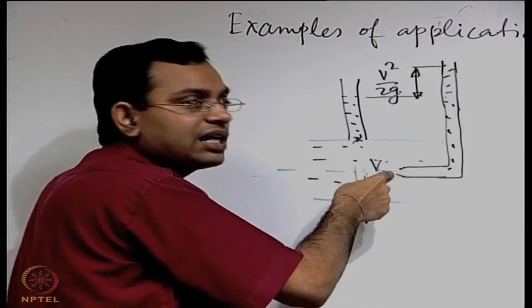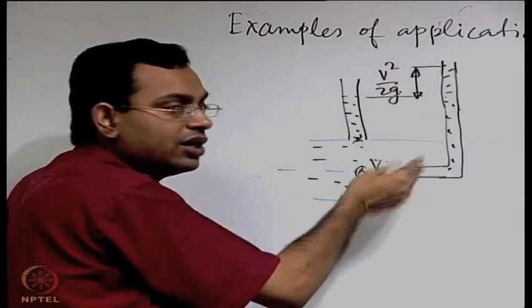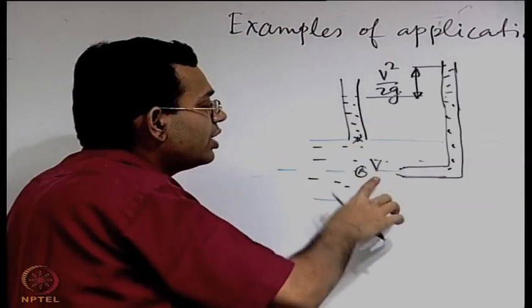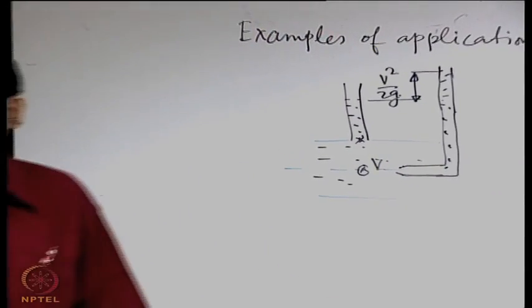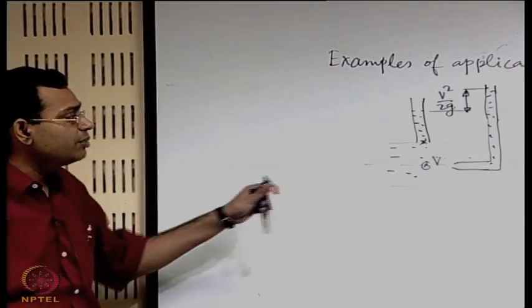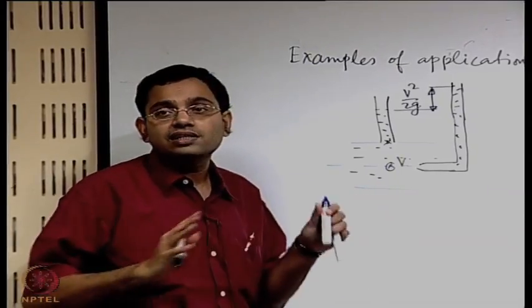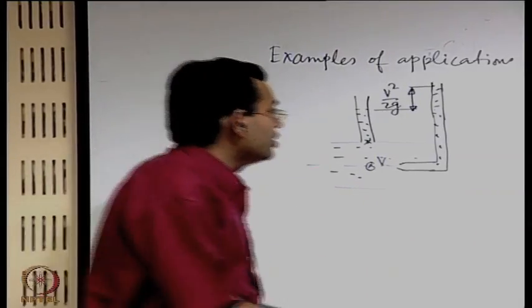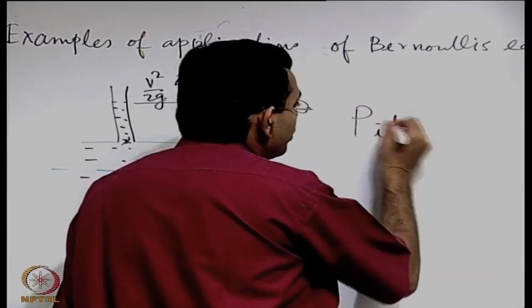because this tube you can put at different radial locations. So this is put at r equal to 0 at the center line, but you can also keep it away from the center line. So at different radii, it will give you a picture of velocity at different radii. So it is possible even to get a velocity profile if this is quite accurate. Of course there are many doubts about the accuracy of such a simple arrangement, but it gives us a conceptual understanding. So the device which is based on this conceptual understanding is known as a pitot tube.